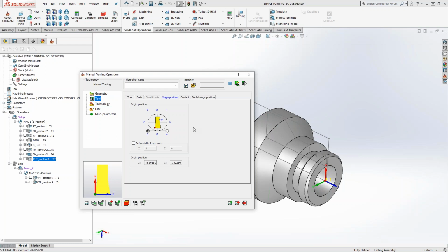I think when this was covered in the CAD/CAM night class, you had the example of turning a surface hardened material. The first couple of cuts had a shallow cut, and then as you get closer to the center, because it's no longer surface hardened, you can take deeper cuts. The way to get that done was with manual turning, because you literally sketch out each pass using SolidWorks sketching. And the tool that you're using follows whatever you've put as your reference point.